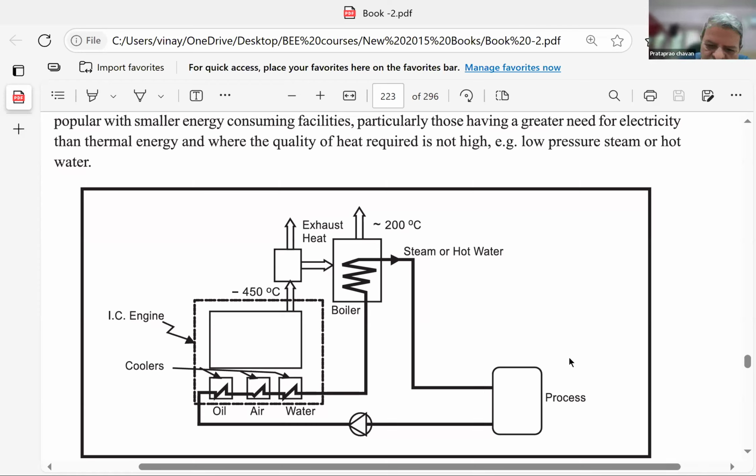Yes. This condensate of the steam is routed through these heaters only for the purpose of raising the temperature before it goes to the boiler. You know what an air boiler economizer is? What do we do in an economizer? We are also preheating the feed water going into the boiler so that the heat generated from the fuel will be less utilized. There will be fuel saving. The same principle here. Yes, sir. Yes, understood. Okay.